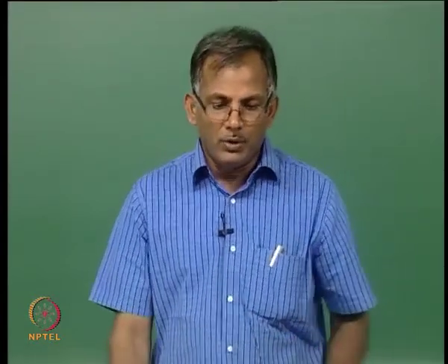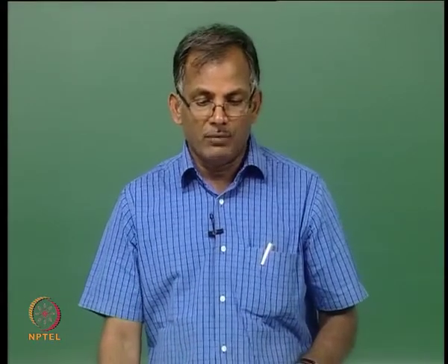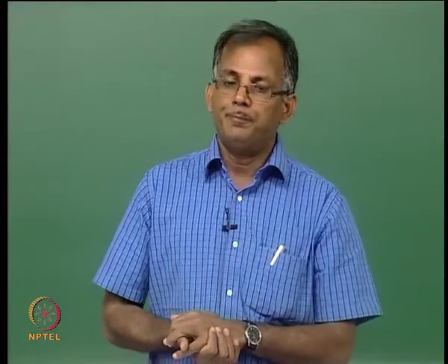Number one, the loads are going to be very large, and also the facilities supported on top are going to be subjected to direct water immersion, which is not very good. So, you may have to change the facilities. That is one side of the story. The second major issue is the stability of the jacket itself. When you subject it to so much larger load, whether it is going to be sufficient, and if you have to check such a platform existing for, say, 30 or 40 years, still producing, what kind of criteria you have to use, you may actually have to reduce the requirements. But then what will happen to a platform if you are planning to install now, whether you need to provide for such.